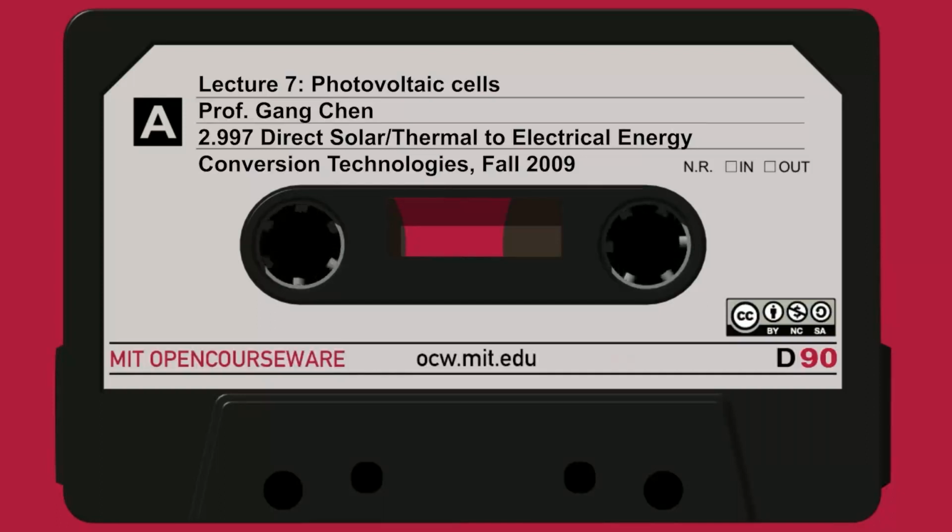Okay. But this is actually showing you a multi-junction. If you look at it, this is on scale, and the top is a transparent electrode. So unlike silicon, where you look at the electrode on top, it's spaced apart, so the electron has to diffuse laterally to the electrode. Silicon is reasonably good in terms of recombination.